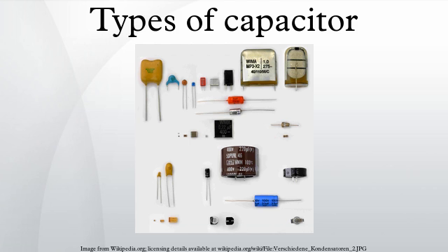Pseudocapacitance. Storage is achieved by redox reactions, electroabsorption or intercalation on the surface of the electrode, or by specifically adsorbed ions that result in a reversible Faradaic charge transfer. The pseudocapacitance is Faradaic in origin. The ratio of the storage resulting from each principle can vary greatly, depending on electrode design and electrolyte composition. Pseudocapacitance can increase the capacitance value by as much as an order of magnitude over that of the double layer by itself.